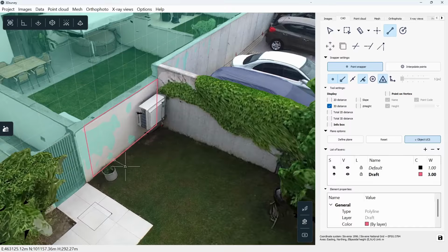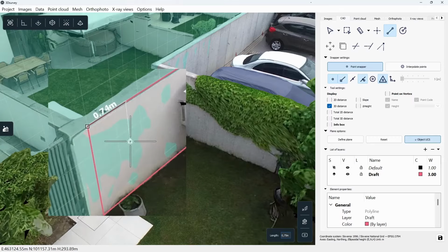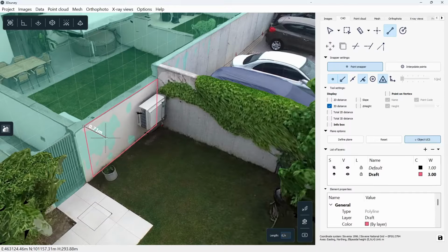Now the interesting part, how do I exit this plane? I just hover over in the direction I want my line to go and look for the inverted T, the perpendicular sign. Again, I use the length input, this time 0.75. From here on, there are a few ways you can go about this. I repeat the 3.0 and finish the upper side.